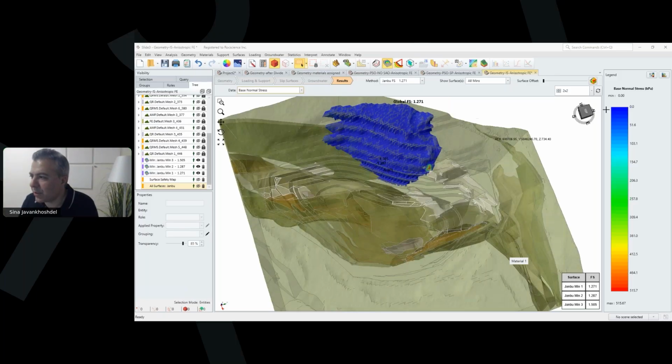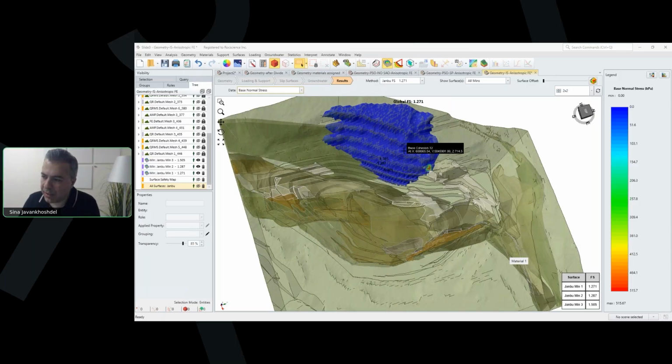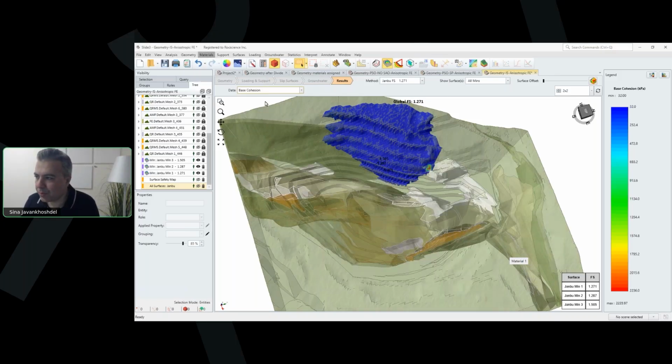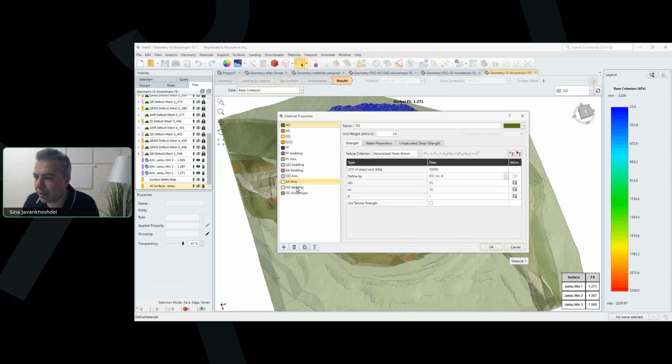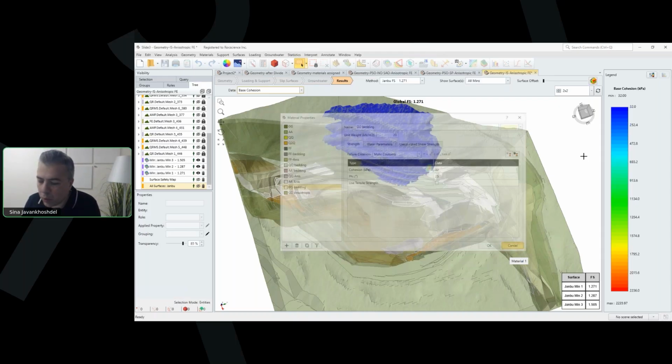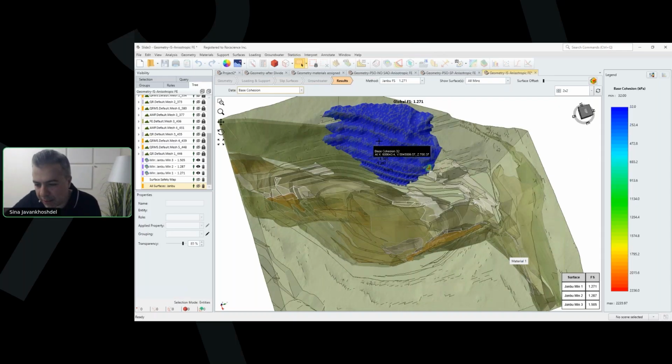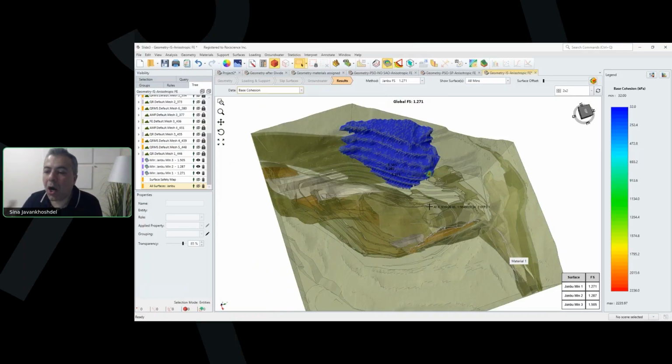you can see that it's 0. So it captures the anisotropy of my base material. So if I go to that material and look at the bedding, the cohesion, sorry, is 32, not 0. It's 32, and you can see that it's blue. So the whole thing is blue. It captures the entire anisotropy bedding of my material. And that's the beauty of how we do the search.